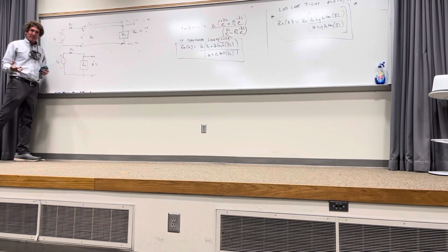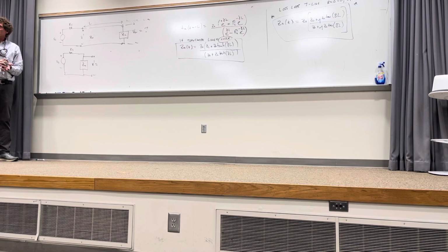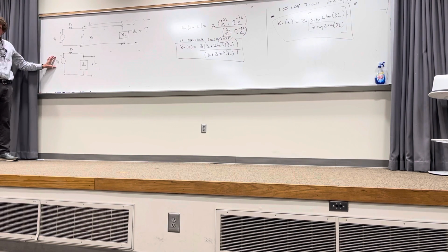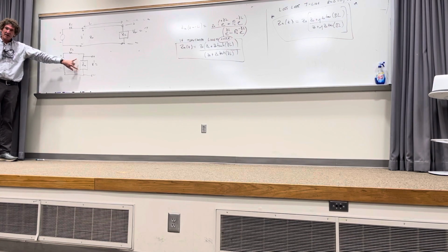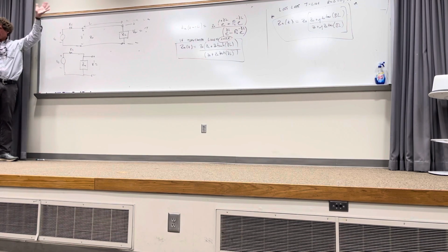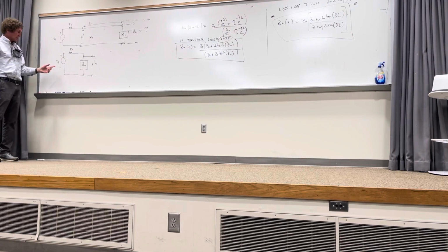So how do you do that? Now, you're electrical engineers, you've had circuits. If this is a job interview, they'd expect you to be able to do this in a blink. How do you do that? What is that? Voltage division. Simple voltage division, isn't it, class? The only thing I do is take this voltage and multiply it by Zin and divide it by Zin plus Rs. How many know that? Right? Some people say I get the current first.